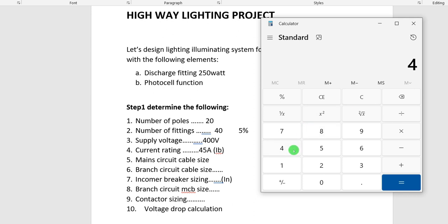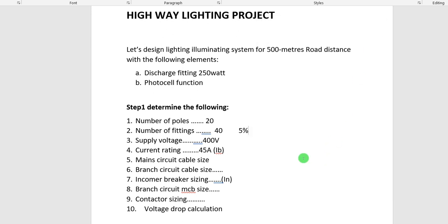So in that case, our 400 minus 20 is going to be 380. So we are having 380 left. Our voltage shouldn't drop below 380. All right. Because of that, we are going to factor in another calculation process that is going to guide us on voltage drop limitation. So how do we now do that?